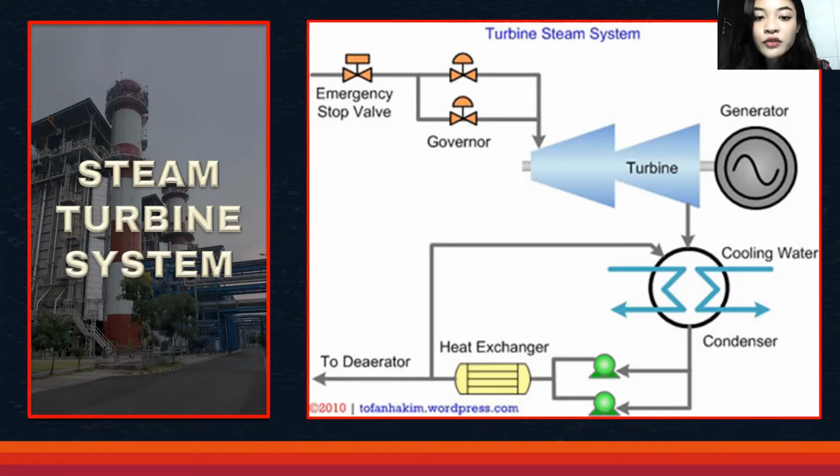Soon after steam enters the turbine, expansion takes place to convert steam enthalpy energy to mechanical energy through several stages. The expansion takes place through a series of fixed plate nozzles that are concentrically arranged within the circular turbine casing and moving blades which are attached to the central turbine rotor. Each row of fixed blades and moving blades is called a stage. Steam pressure and temperature will dramatically reduce when it reaches the last stage.